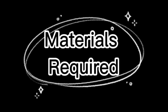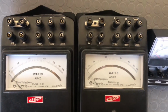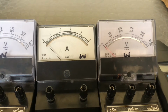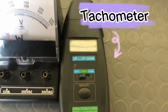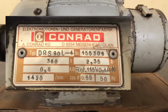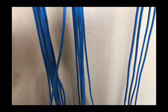Materials required for the practical are a three-phase power supply, two 0 to 350 watt wattmeters, two 0 to 500 AC voltmeters and a 0 to 5 AC ammeter, a tachometer to measure the speed, and an induction motor rated 380 volt and 2.35 ampere, and some 2.5 mm square connecting wires.